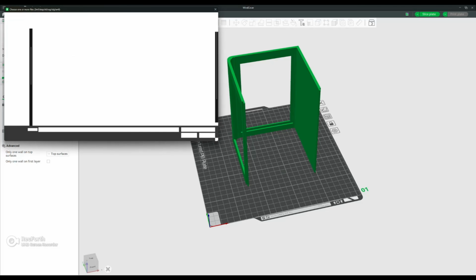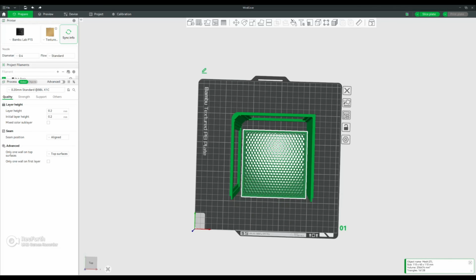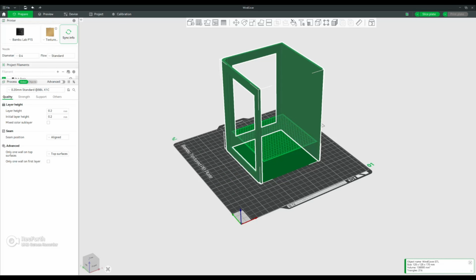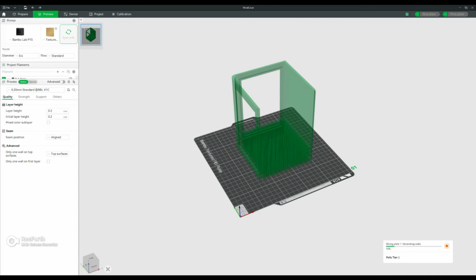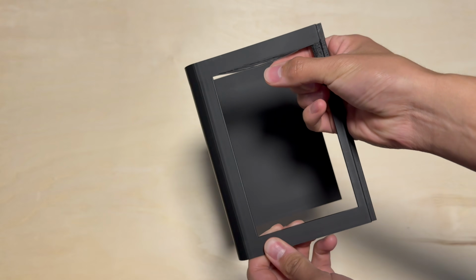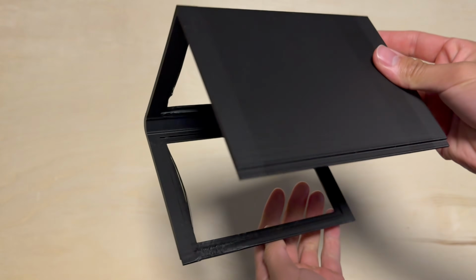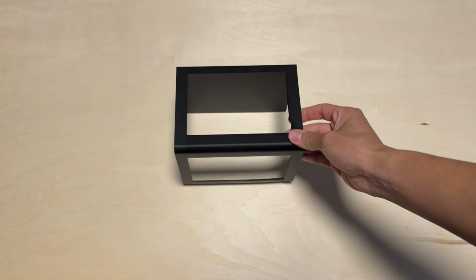I got a bit impatient while slicing the print files, and tried to print the mesh block and the cover at the same time. Given how thin this part was, I probably should have just taken my time and printed it separately, especially since even by the looks of it, you can tell it would probably fail. Unsurprisingly, near the end of the print, the cover started warping, and by the time it came off the bed, it had visible imperfections. The glass panes weren't going to sit flush in a warped panel, so I had to deal with that before I could assemble anything else.